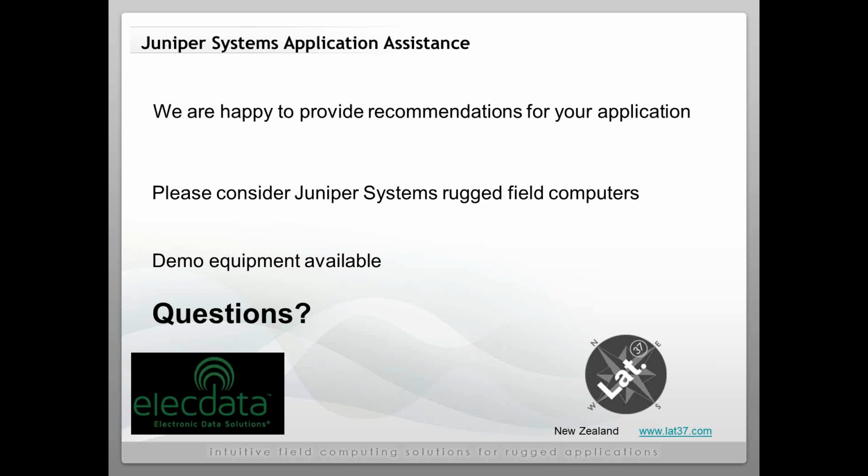Yeah, so with the fisheries types of applications, typically in a very low frequency scenario with 134 or even the older 400 kilohertz, we have many examples of pit tag readers. There is an RS-232 serial port on the top, and just like you would connect to a GPS or some other type of external water quality sensor, it's the exact same process.